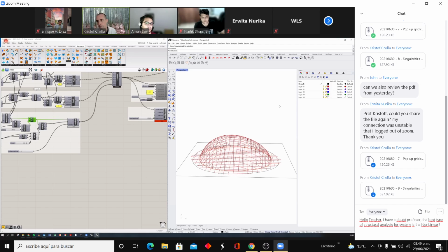So you can approximate many geometries, but you cannot make any geometry from bamboo, or from a bending-active shell. It's almost like a balloon. If you stick a balloon through a ring, it will take its balanced shape, but you can push it in one point, and it will just deform in another part. Or you can put a tape over it, and then you'll get two bubbles. Similarly with these types of structures, you can put a metal cable over it and tension that cable to create a deformation. That's all possible. So you still have quite a bit of flexibility to play with.